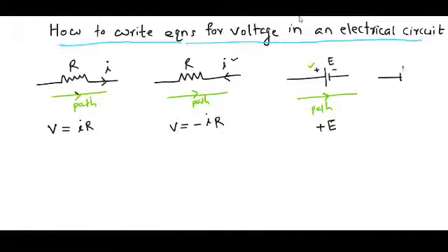If this is a battery whose terminals are negative and positive, and the path we consider is from left to right, then while coming along this path, first we will see the negative terminal. In such a case, we have to write the battery potential E as minus E.